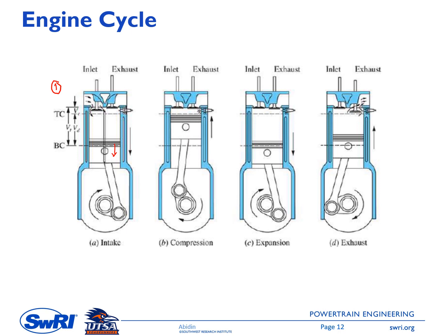So let me repeat again, just to make sure: the piston moves down, the chamber volume increases, and thus the chamber pressure decreases. Then there will be a pressure difference between the intake manifold, somewhere upstream here, and the pressure in the chamber. And then as the intake valve opens, the mixture enters the chamber, okay, and then at some point the piston hits the bottom center. The piston then moves up doing a compression stroke.